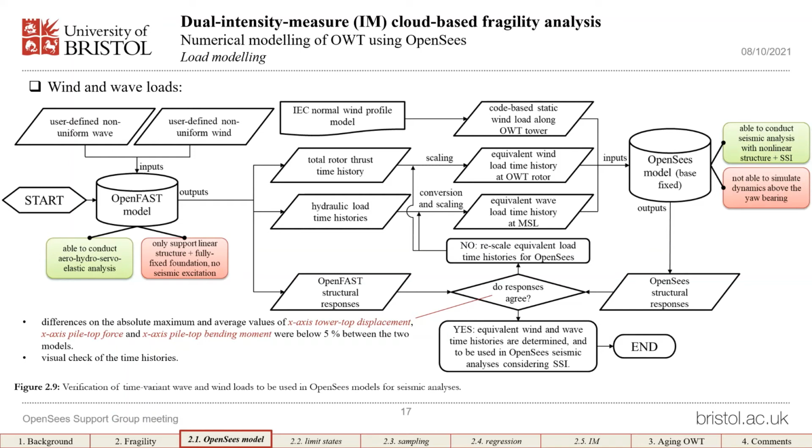Okay, so the computational time for 300 analyses. Of course, you see that we have all these processes ahead of the actual time for the OpenSees model, but for only the OpenSees model, on a pretty high-end desktop computer for these 300 analyses, I think it takes about 1 day. Yes, thank you. And you obtain the fragility surface in terms of wind load and earthquake intensity measure, I think. What about wave load or wave height, I mean?